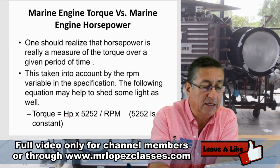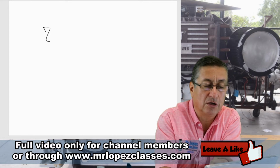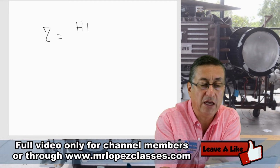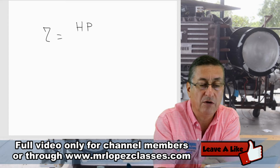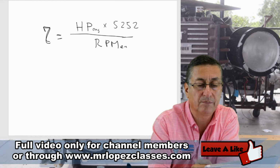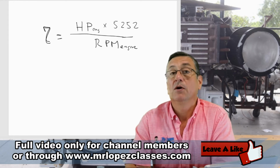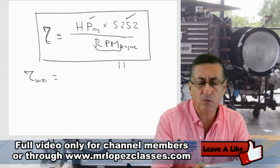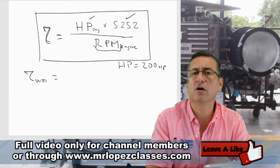The formula states that the torque should be equal to the horsepower of the engine times the constant 5252, and divided by the engine RPMs. Alright, my friend, this is an important formula. Suppose that we have an engine with a motor of 200 horsepower. 200 horsepower, this is the power of the engine.